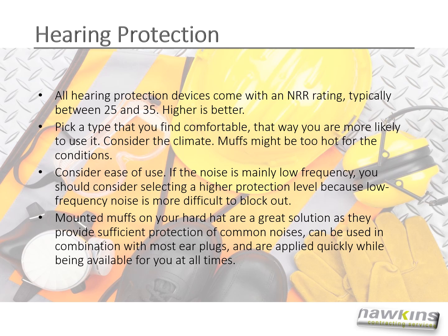If the noise is mainly low frequency, you should consider selecting a higher protection level because low frequency noise is more difficult to block. Mounted muffs on your hard hat are a great solution as they provide sufficient protection of common noises, can be used in combination with most earplugs, and are applied quickly while being available for you at all times.